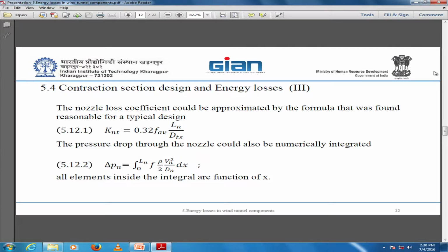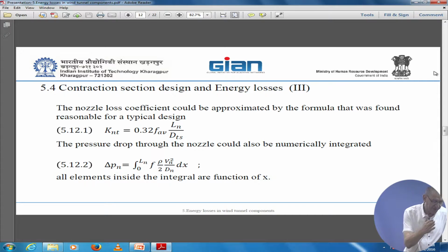So first thing, we put there a honeycomb, to make sure that any flow which is not in the main direction will straighten. And we saw it. As I told you, I recommend, and we do it, for every element like this, we put it in a drawer so we can check how it reacts without a mesh, with a mesh, without honeycomb, with honeycomb.